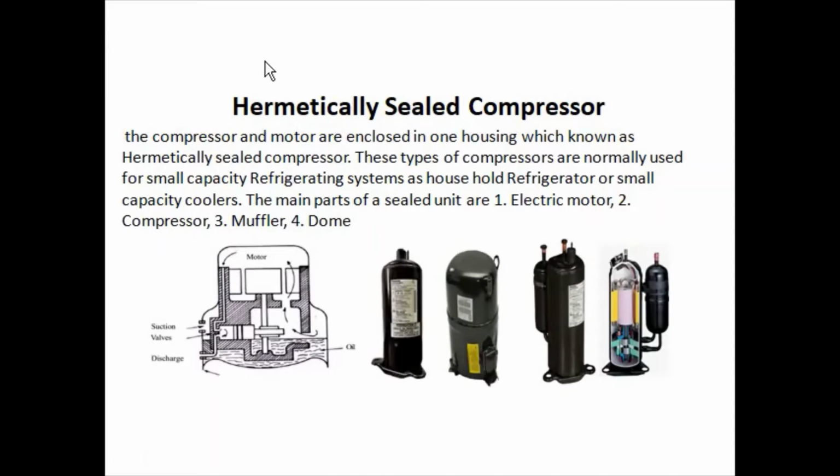For a semi-hermetic compressor, the motor and compressor may be separate, may not be in the same case, but for a hermetically sealed compressor, the compressor and motor are enclosed in one housing. That is why it is known as a hermetically sealed compressor.